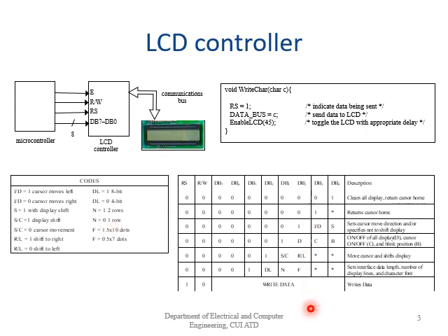DB2 is F. If F is equal to 1, it means that we will have resolution of 5 by 10 dots. If F is 0, it means that we will have resolution of 5 by 7 dots. So finally, if you want to write something, we must have RS signal 1 and read write 0, and then finally we can send any data that we want to write.